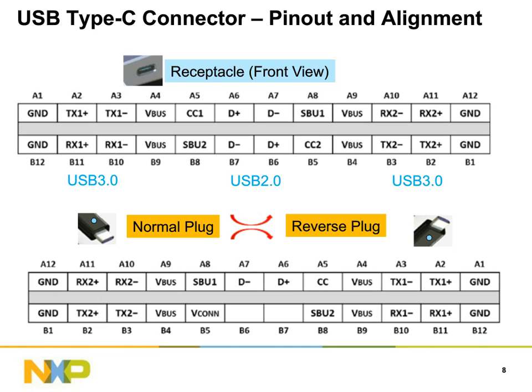What this tells us right away is that from a system design standpoint, we will need some data switches in the path to be able to support this flippability of the connector, so that no matter how the plug gets plugged in, we are able to identify which data is on which lane and route those pins to the appropriate pins on the chipset or whatever host controller we are using. Hopefully this gives you a nice picture of how we can do all these different things at the same time.